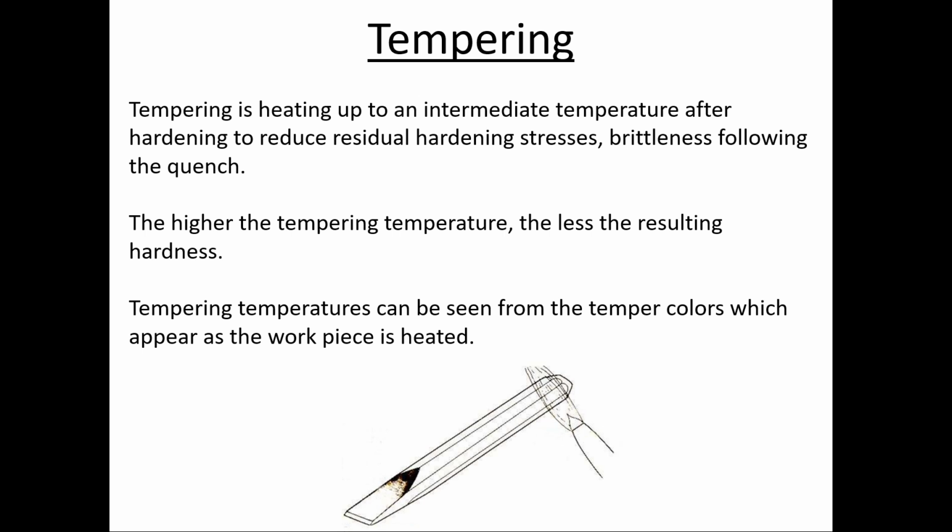If you don't temper, you'll end up with something breaking very easily, even though your weld was perfect. It might just be sitting there under stress and it needs to be relieved. And there's ways of doing that. If you have that oven, for example, that's sitting at about 400 or 500 degrees, that's about where I want it to be. What I do is I shine it up. I take it over to a sandblasting booth, or I take it to a buffing disc, and I shine it up and get nice shiny steel after I've gone cold. Then I put it back in the oven, and I leave it in the oven until it turns straw, a little bit of a yellowish tint to it, and then it'll be fine.